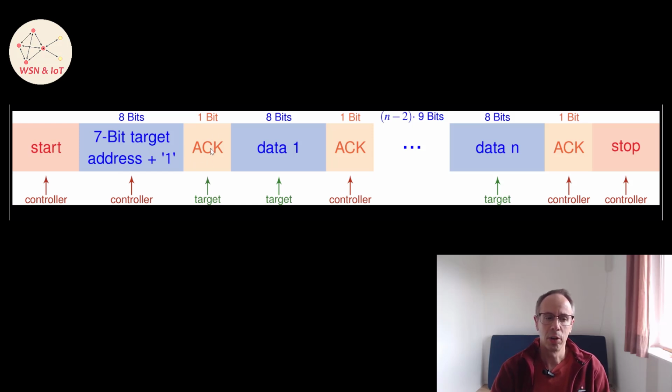We get the acknowledgement from the target, and then the target sends the data until it's finished. The controller then acknowledges this and sends a stop condition.